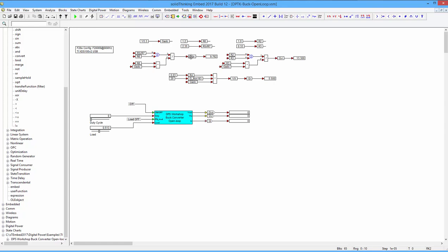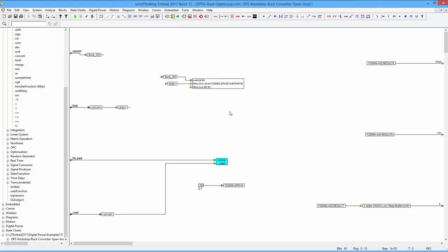Here we've worked out the necessary coefficients based on the resistance values on the schematic of the buck converter design kit. This is the ADC gain, because we're using 3.3 volts and we're scaling that to 1 volt. The R5 in parallel with R7 is actually two 4K7 resistors. R6 is a 1.2K resistor, which is giving these values here. Same with the input voltage scaling, and the current scaling is here. Okay, now this should give us the correct values.